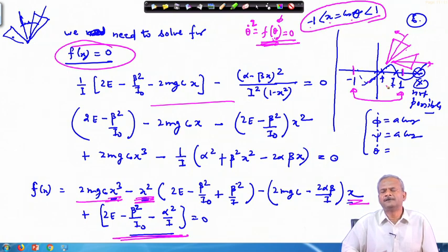mass we assumed to be 0, and therefore its moment of inertia was 0. That was a simplified condition; we will no longer assume that, because it is never true in reality and it is impossible to make it massless. Once we put in a system where the frames also have weight, there will be motors actuating the frames, and those things need to be accounted for. Then it is housed inside the satellite, which is itself rotating. So the whole equation gets very complex, and then you need to solve it.